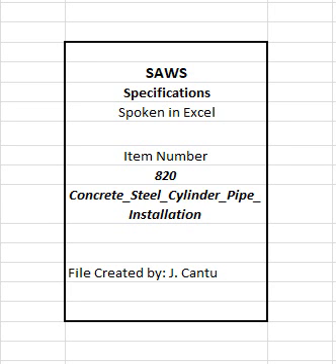10. Submit inspection procedures to be used by manufacturer for quality control and assurance for materials and welding. 11. Submit standard repair procedures that describe in detail shop and field work to be performed. 12. Steel reports as required in AWWA C301 or AWWA C303. 13. Hydrostatic testing, acid etching, dye penetration, magnetic particle, and X-ray weld test reports as required. 14. Compressive strength, 28-day, test results for each type of coating, lining and core mix design.